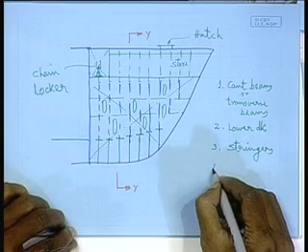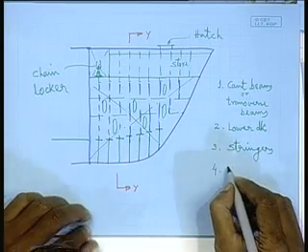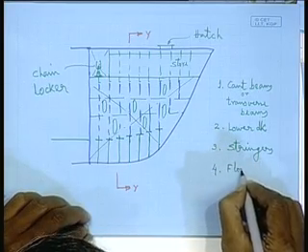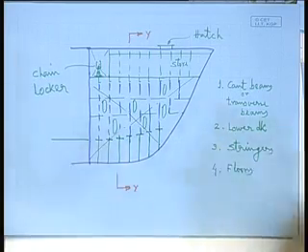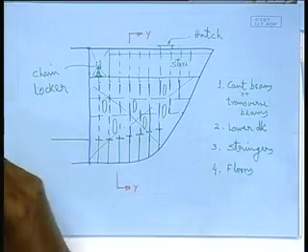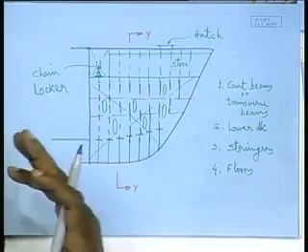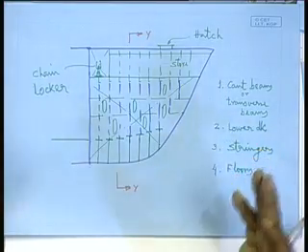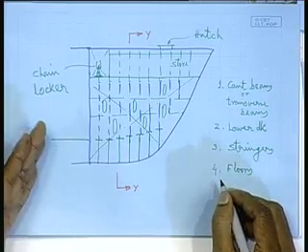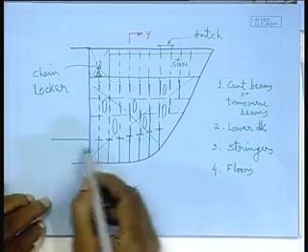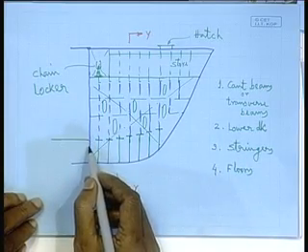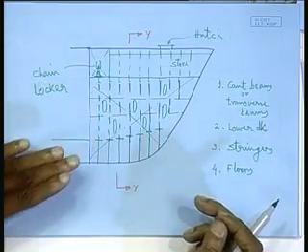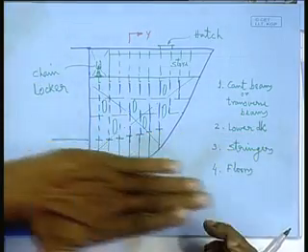Then we have seen floors, in the same concept as in the double bottom. There we had the center girder, it came up to the forepeak bulkhead, and then we stopped the center girder, because here the bottom shell is going up. So taking the center girder further is not possible.